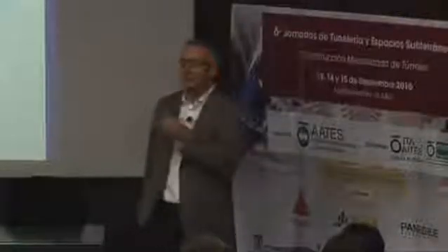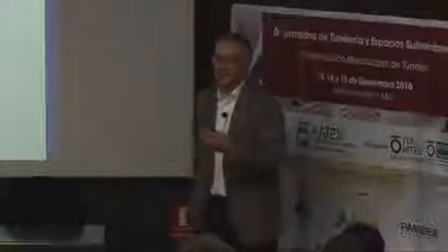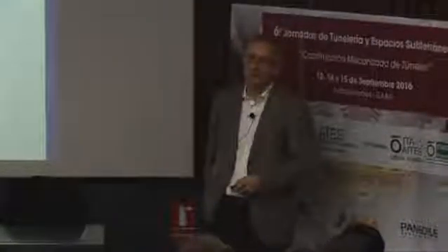So our recommendation is, if there's no direct danger around, then move the cutter head, go ahead. Nothing is better for tunneling than advancing, so move the TBM out of that and get up again into a controlled area.